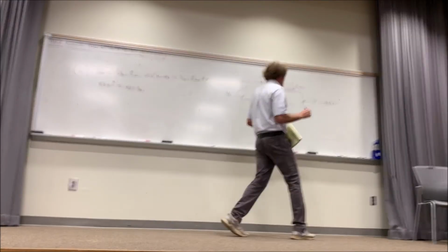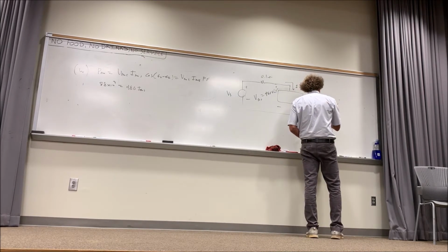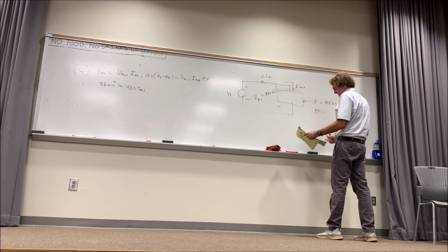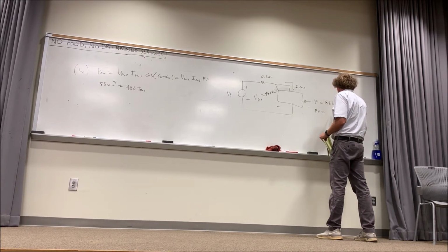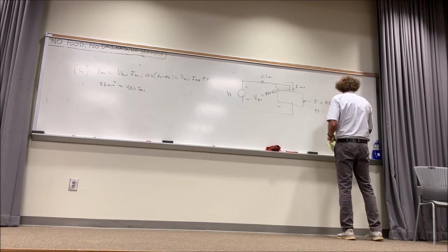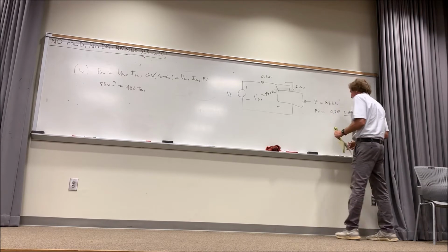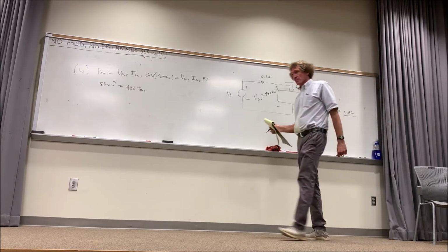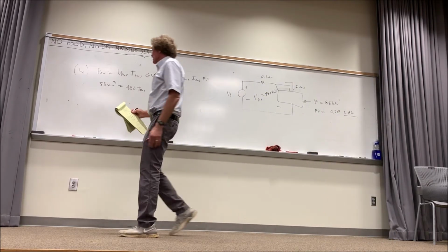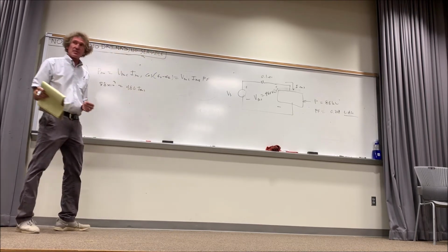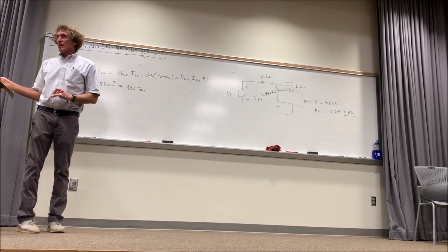And there's going to be a power factor here, in this one, of 0.707, and it's lagging. Write the word lag. That means the current is going to be behind the actual voltage. Now the voltage is at 0 degrees. The current's going to have a negative angle associated with it. You follow me, class? Please watch this.